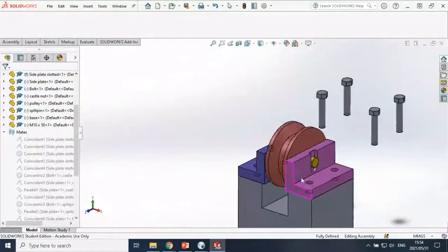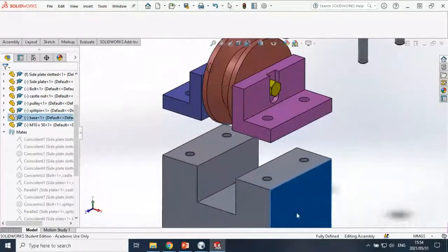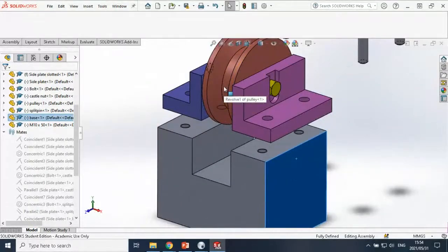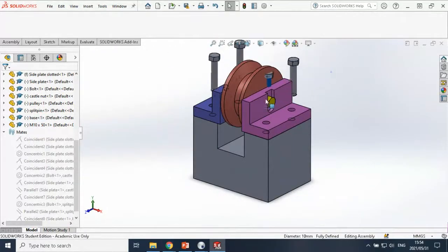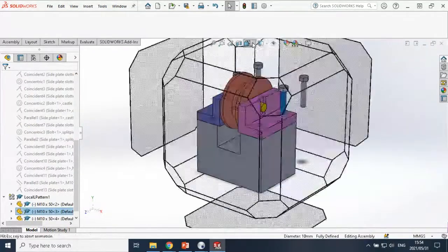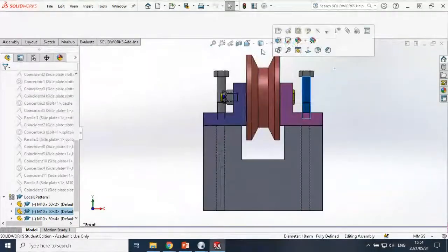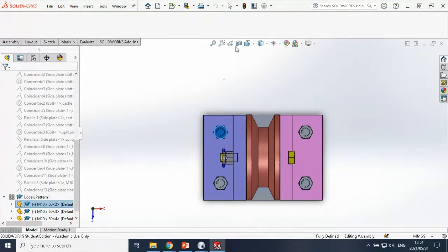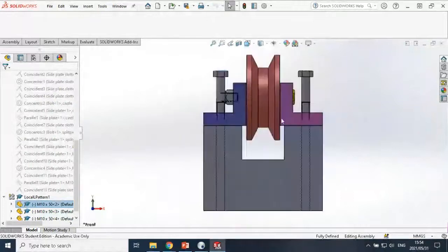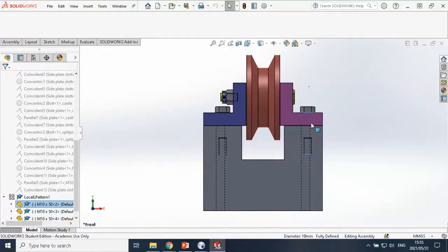Okay, and now the problem with this assembly still is this block can fall off. So standard components are then used, M10 bolts in this case, we position them above there, then we screw them down into the threaded component, something like that.